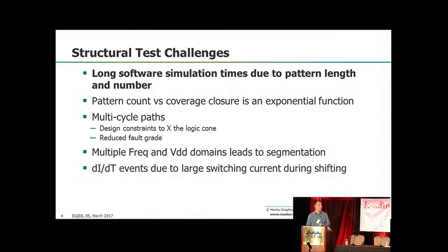You've got things like multi-cycle paths that you can't scan through. So what your ATPG tools traditionally do is they just mask that logic out. So now you have X's in your pattern, so you're not testing any of those faults. A lot of these SOCs have multiple frequency domains, multiple VDD islands, so you have to make sure that you scan only within those partitions. And finally, large di/dt events, where because you're scanning all this data into these highly compressed shift registers, you could have a voltage sensitivity on one of the nets where if the rail collapses, you're going to get a false fail.